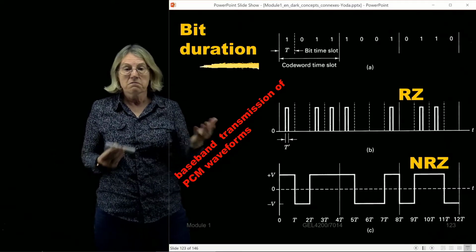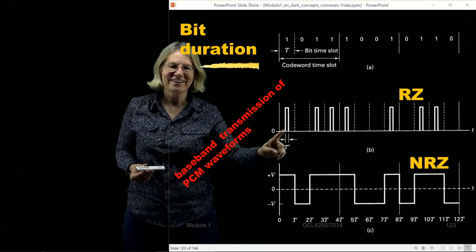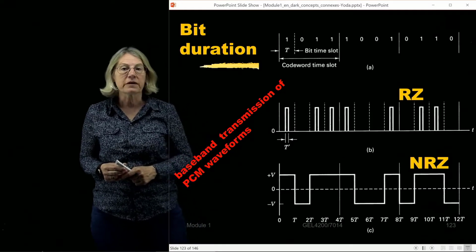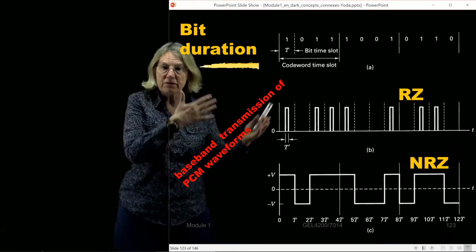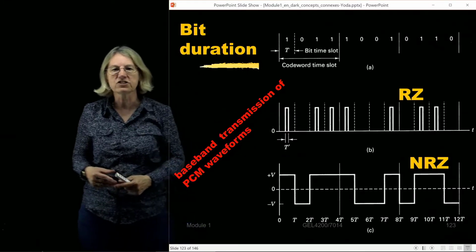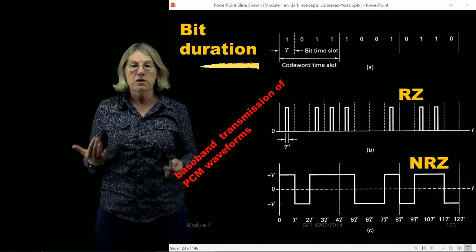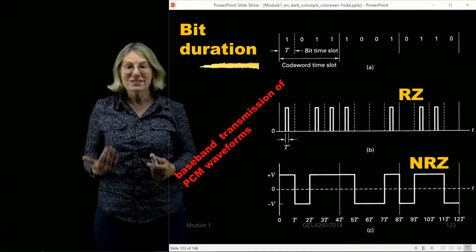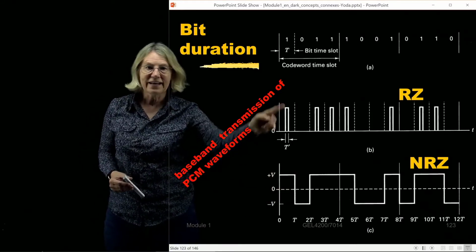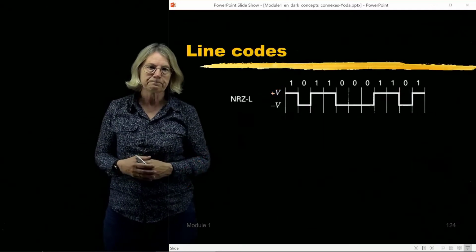Okay, so there's a couple different ideas here, but clearly there's this return to 0 where not the whole time of a bit is used for the voltage that's being transmitted. So that gets an example of RZ and NRZ. And of course, this is like a third, but it could have been any percentage. That's a parameter I can use. So this is one idea of, even if I'm using PCM, there's different ways I can use it. I can use it this way, antipodal, use the whole time, or not antipodal, and use just a small percentage of the time. That's one possibility.